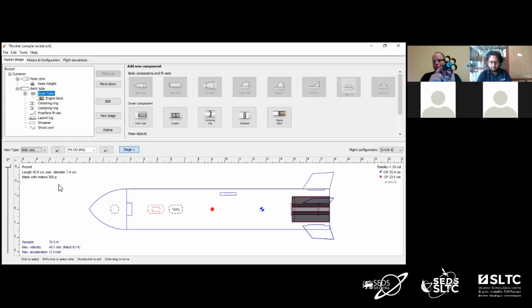If you get this tube part figured out and cut some little sections of tubes, that's very adequately going to serve the purpose of shifting your center of pressure back. That's what we need for stability. This is actually a very stable configuration. So maybe a little more simple depending on what your materials limitations are, but that's an option.